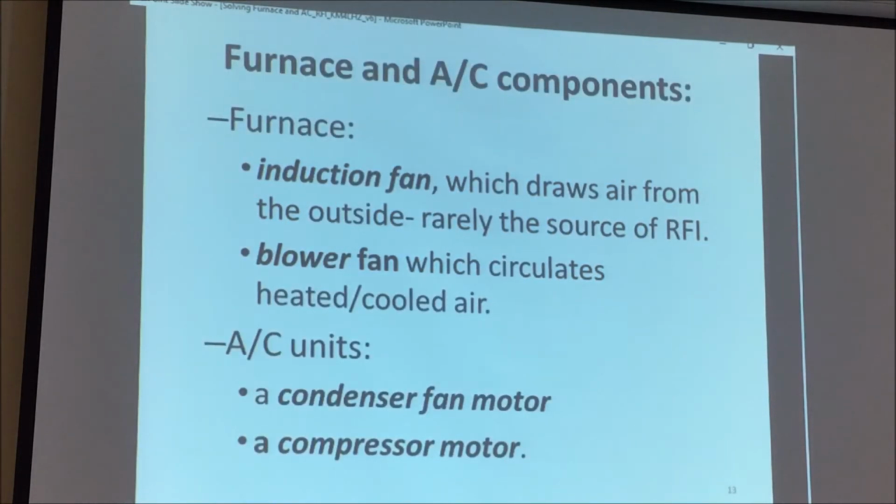First of all, I want to talk a little bit about furnaces and AC components. A modern furnace has 2 fans. One is called the induction fan, which draws air from the outside. In this version, I said it's rarely a source of RFI. But just today, a Lennox engineer looked at this and he said, more and more of our induction motors are actually high efficiency motors and are as likely to be a source of RFI as any of the other motors. So I really should change that particular bullet.